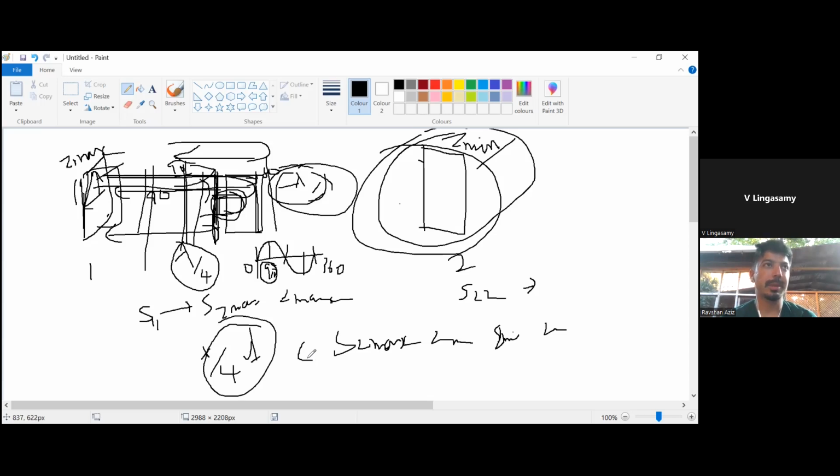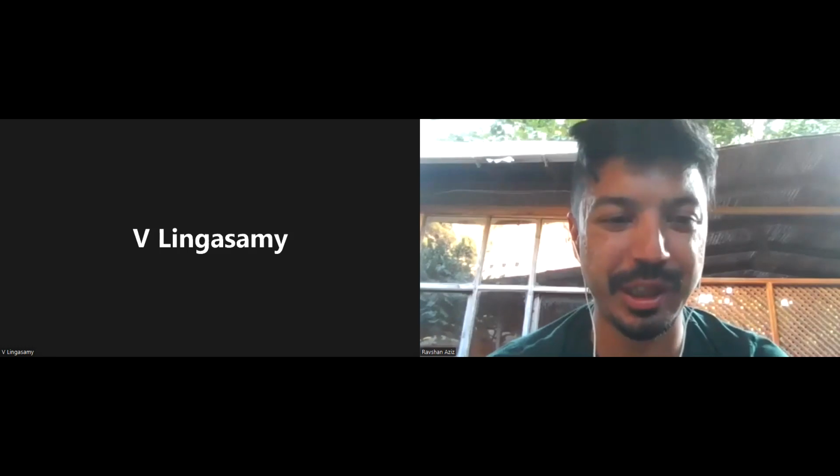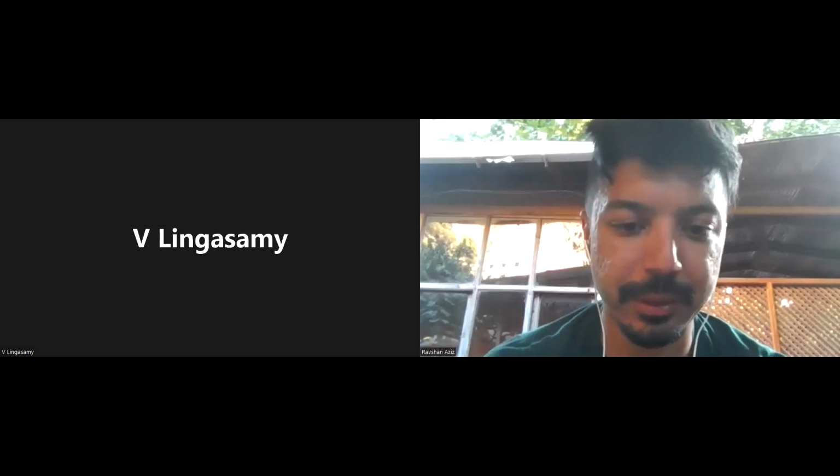Okay. So, for example, if I am investigating the phase responses based on CST Studio for different graphene chemical potential levels, it's better for me to use the lambda by 4 distance and generate a graph based on that frequency.